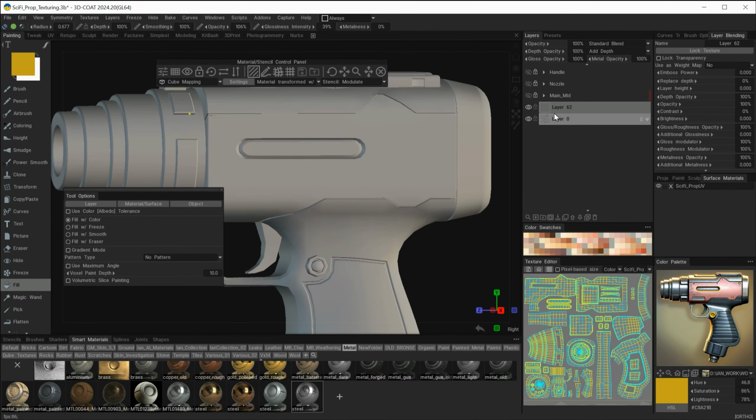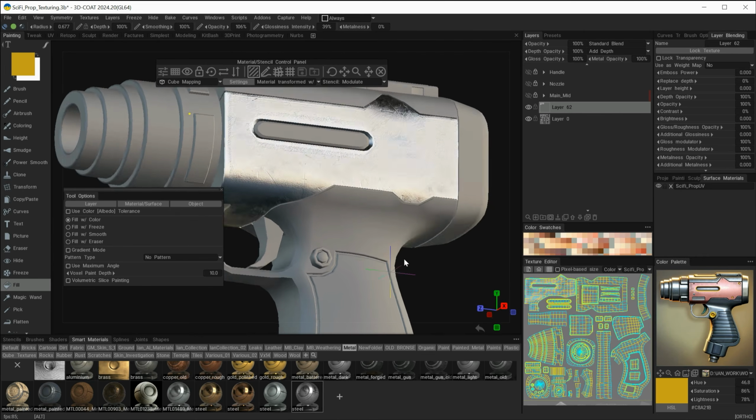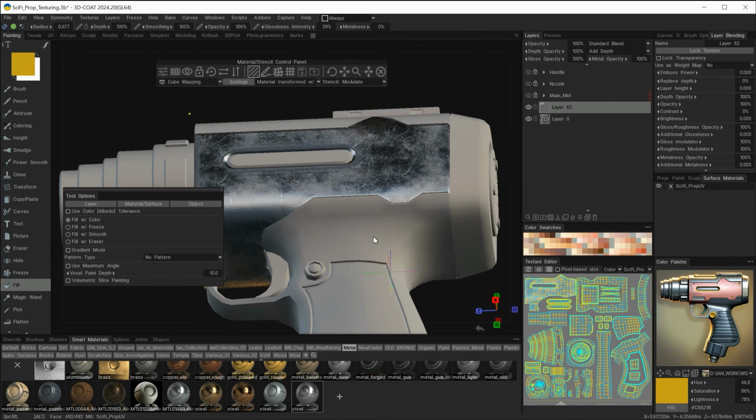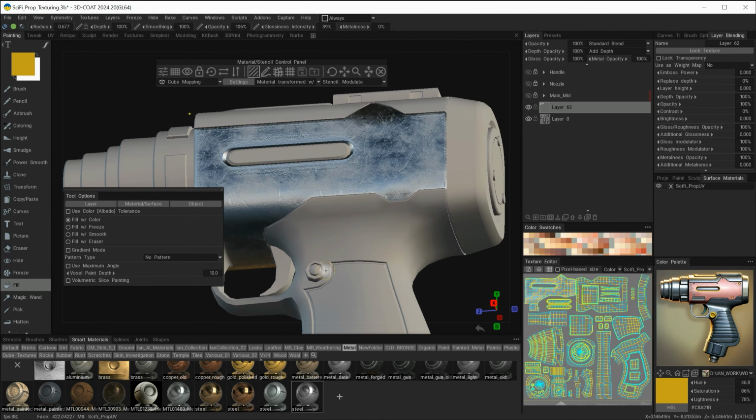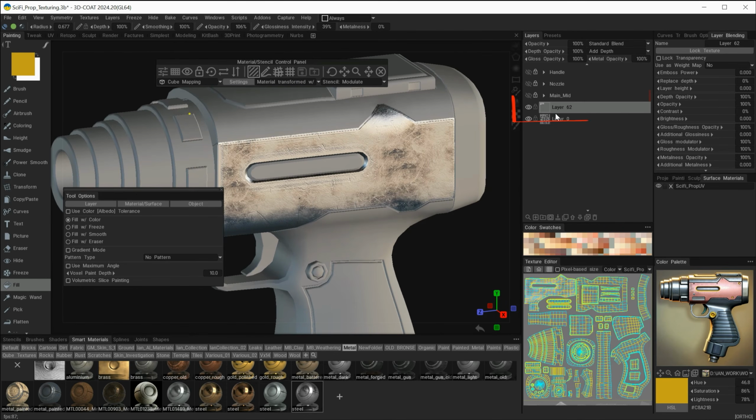All I'm going to do now is click on this UV island. Now you can see I'm getting some reflective properties with scratches and a surface that's representing this steel. I'm on this specific layer that I've created called layer 62, keeping this within the boundaries of the UV area that I'm selecting. This way I have a lot of control over how this can look.